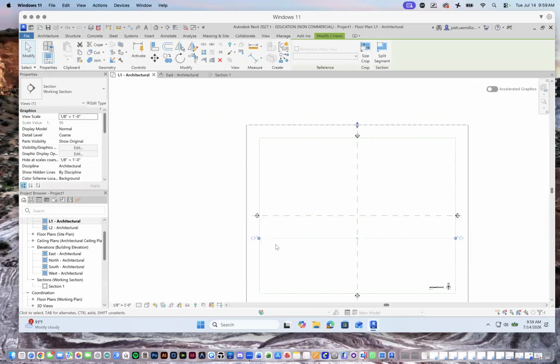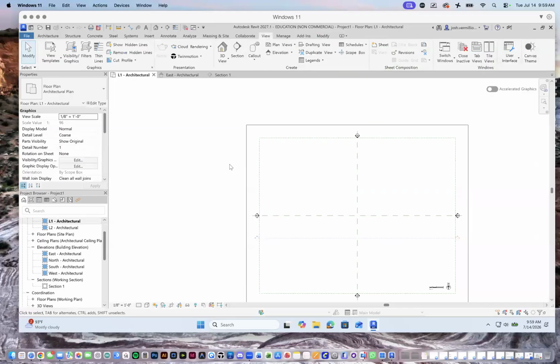So here's what I want to do, and I'll probably have to re-explain this over time and keep reminding you. We're going to take the site information from Forma and link it up into Revit. If we ever need to edit the site, we're not going to edit it in Revit. We go back to Forma and edit it, and then next time we open up Revit, we'll see the changes have updated, because it's linked.